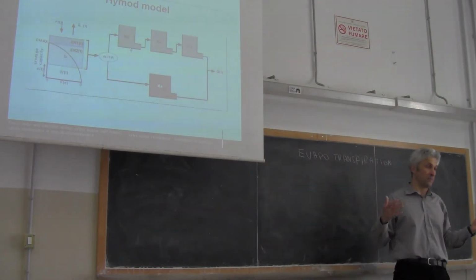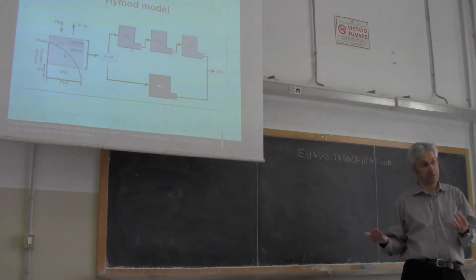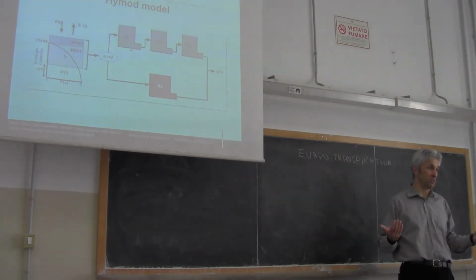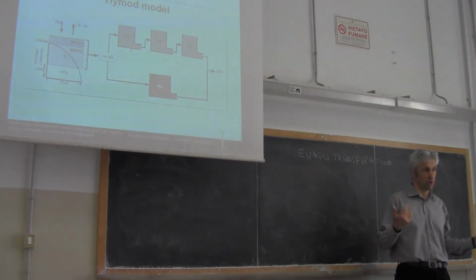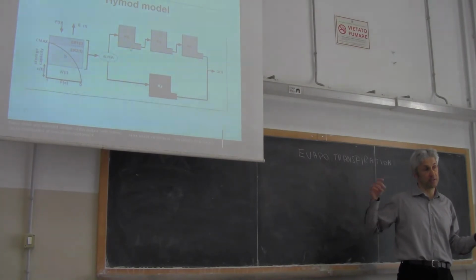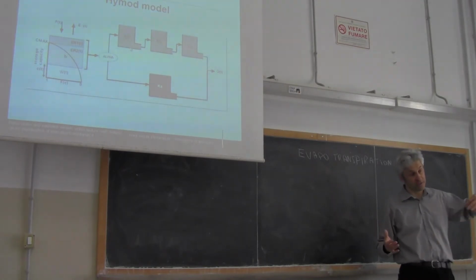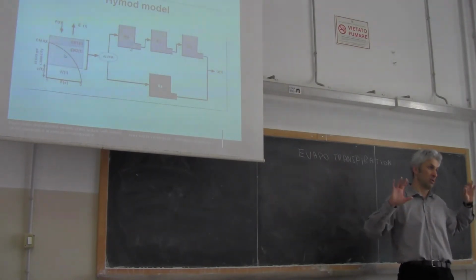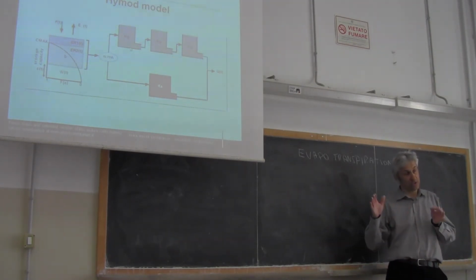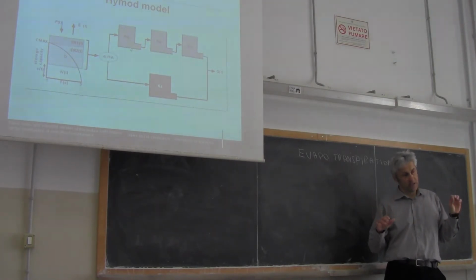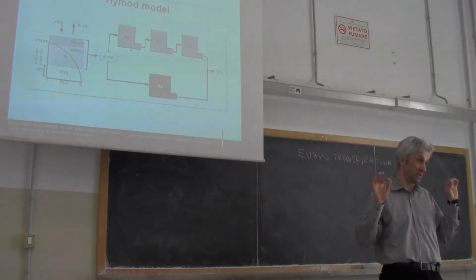To give you an example, in some cases wind is highly effective on evapotranspiration, but in some cases we don't have wind data, and therefore we have to use an empirical formula for estimating evapotranspiration that doesn't take wind into account, because we don't have wind data. If we have wind data, we can use a more detailed formula. So there are several formulations, as I said, which give you an estimation of evapotranspiration with respect to a reference situation.